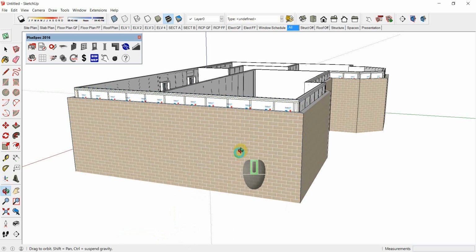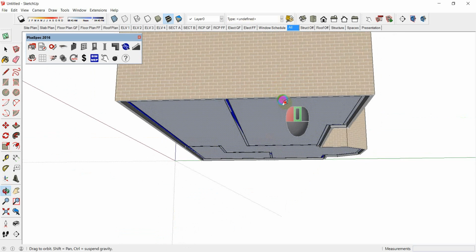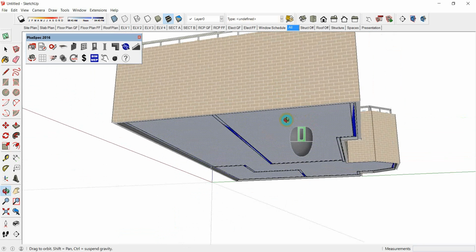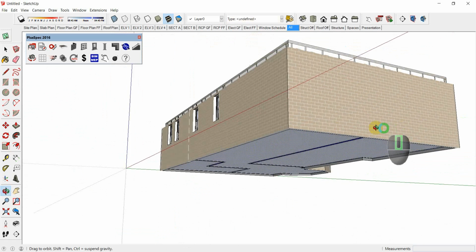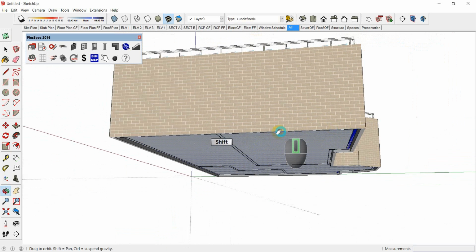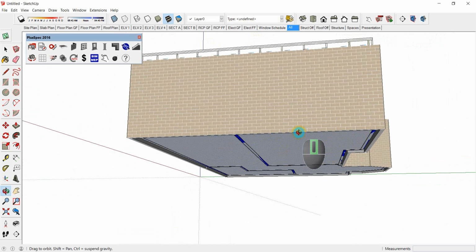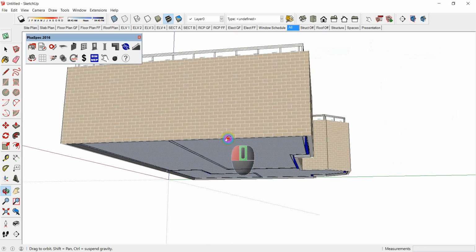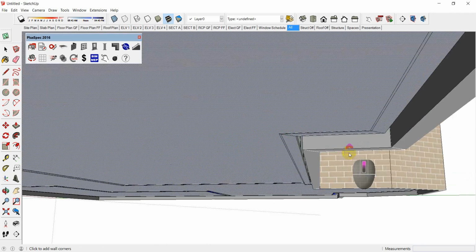It's pretty easy. Look, first time you do it, watch this video. Navigation is probably the hardest thing. Basically you can see the center button of my mouse is green, and I'm basically just pushing that down. If I want to pan, I can push shift, it'll move me left and right, or depends on your fingers. If you can push two buttons at the same time, you can pan like that. Just makes it really easy. Get used to zooming in and out.